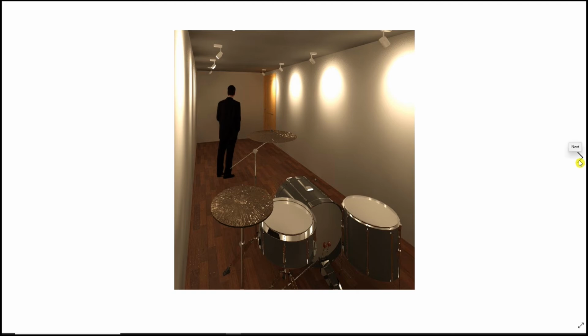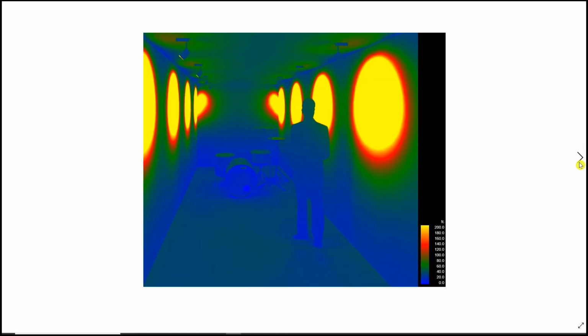What's also interesting about Revit is, and I won't go into any details here in terms of how it works, but what it lets you do is some photometric analysis. So what this is showing you, and it looks like one of those infrared heat guns, is similar, but the color code here is foot candles. A foot candle is an even amount of lumens across a square foot, and it's used to judge the quantity of light at a workspace or a wall or a floor.